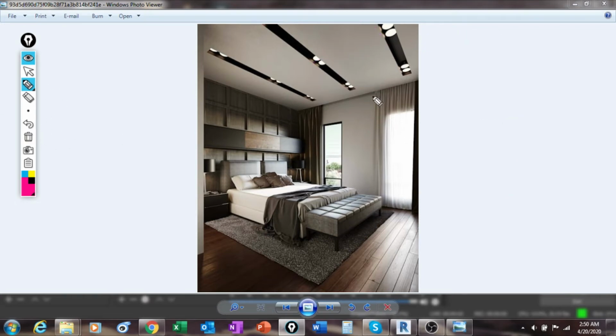For this, we're gonna have to work with nested families. Okay, so we're gonna need two families to achieve something like this. First, we're gonna need a family, a generic model ceiling base. Okay, so that allows me to create this box. So that's going to be one family, family number one.